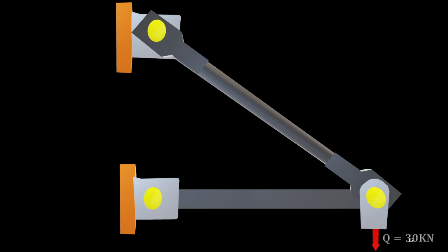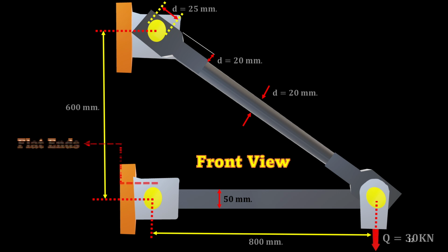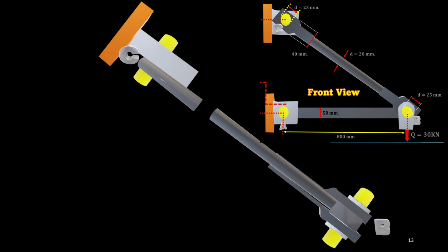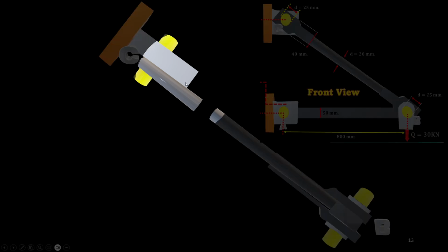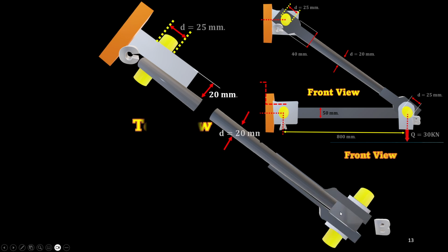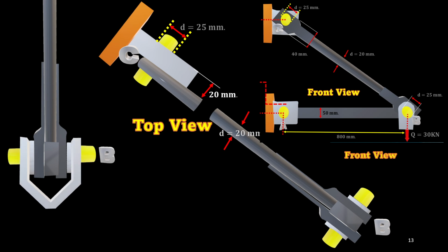And also in the links, as soon as you have the different views like front view and side view, the diameter of the bolts, the connection supports, the condition of the supports, and the different components like in double shear and single shear. If you have a clear understanding of those connections, it's very easy to move on and determine whether it's in double shear or single shear, and then simply calculate forces in members, pins, and different parts of the component.